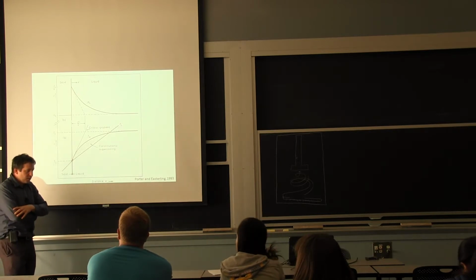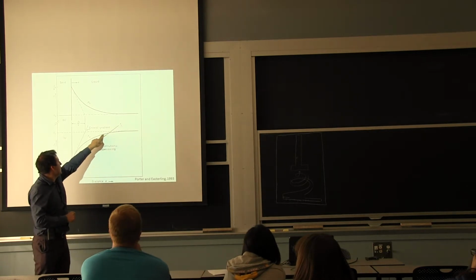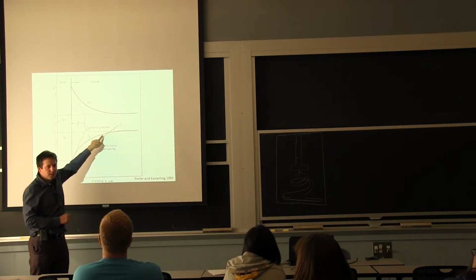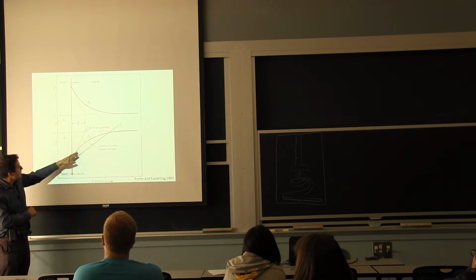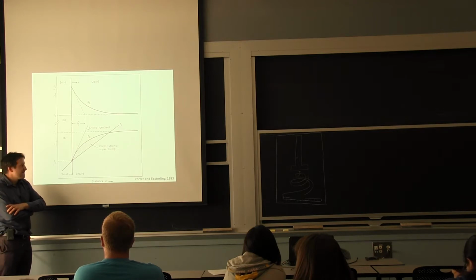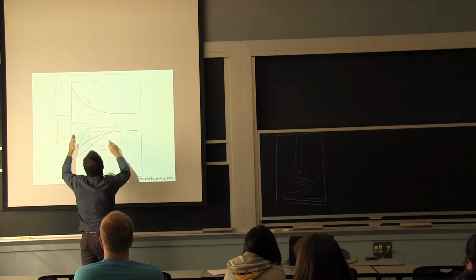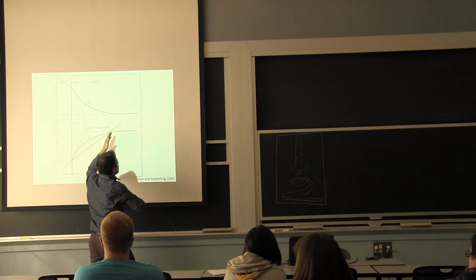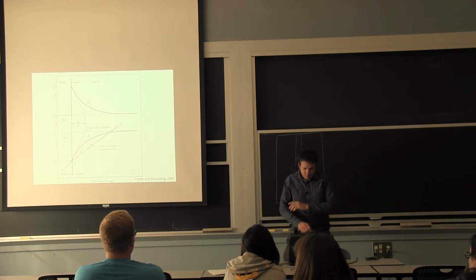So it's a competition between the thermal transfer and the composition transfer, and that's the one we're showing here. Because there are more elements close to the front, the temperature of solidification is lower. So we're all looking very close to this interface. We're not looking all the way to the end of the alloy.